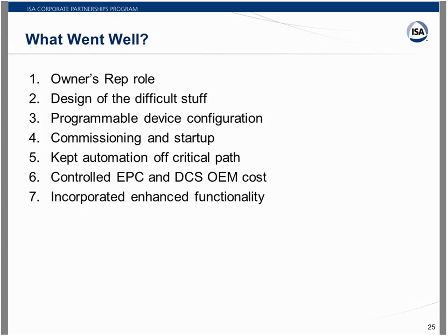Design the difficult stuff. I mentioned the tasks that the automation owner's rep took on themselves. One thing that comes to mind is that Profibus network. That was pretty complicated. It was a technology that's not so common in the U.S., so having that expertise in-house in the automation owner's rep made them uniquely qualified and well-suited to do some of that more unusual design work.